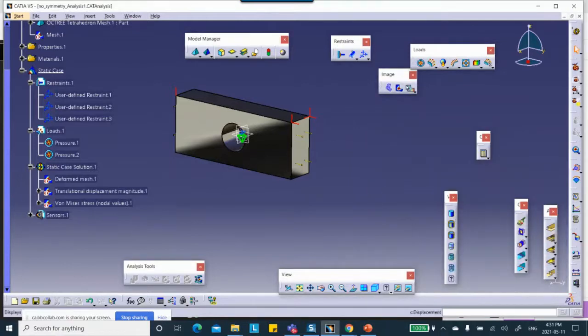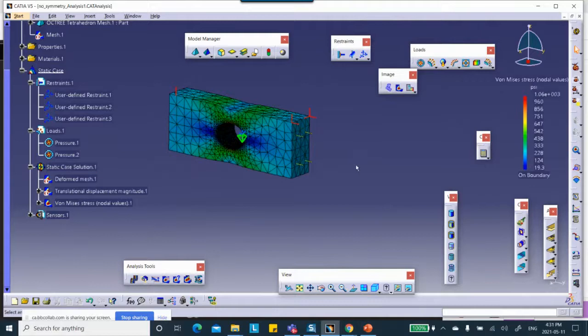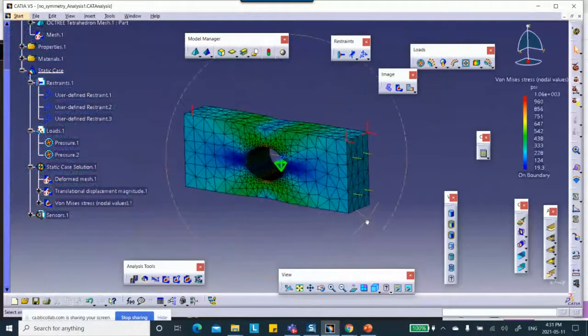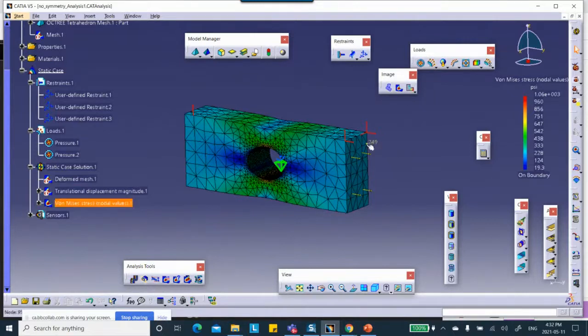Done? Here's the deformation. Let me plot this. Look, there is no bulging here. Okay? Well, first of all, the moral of the story is that if you can avoid distributed load for a real problem when they pay you for something, avoid it, because for solid elements it may cause hot spots, and those hot spots are not physically possible, because there is no such thing as a concentrated force or an edge force or a face force. There's pressure, and that's different from the way that thing is operating.